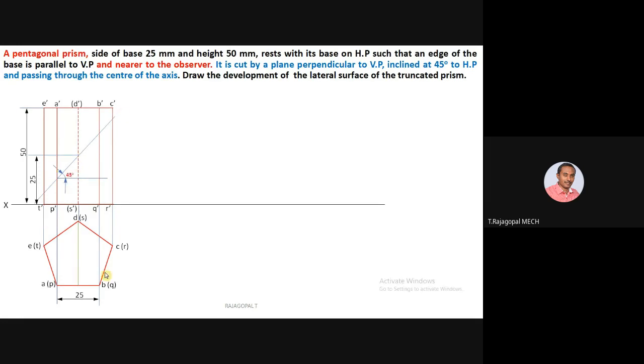So this is our section plane. We have to transfer this thin line into the section plane representation, with a thick line followed by a dot and dash, with a small dash at both ends of the section plane line. Now you know the removed and remaining portions of the solid. The top is the removed portion, and the bottom is the remaining portion with respect to the section plane. We have to convert the remaining portion of the solid into thick lines. So I transferred all the longer edges into thick lines.